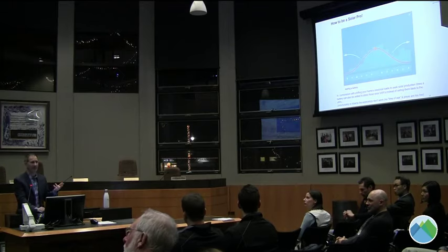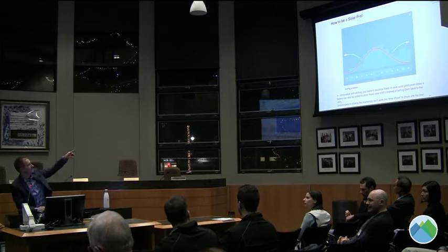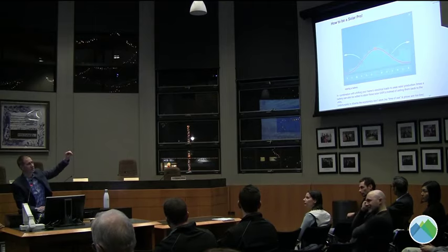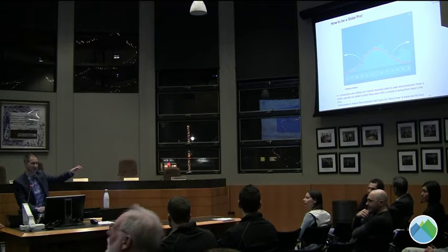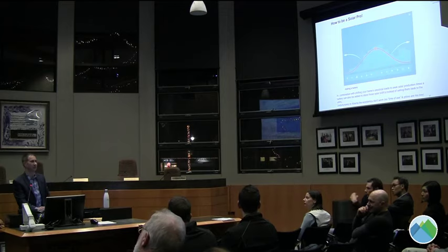So why might you add a battery? Well, theoretically, you could grab that excess production in the middle of the day, and this whole yellow line is dropped. We probably should have it showing a bit higher here. And we could choose to arbitrage those kilowatt hours, grab them, stick them in the battery, and choose when we want to use them versus shipping them back to the grid for a lower price.